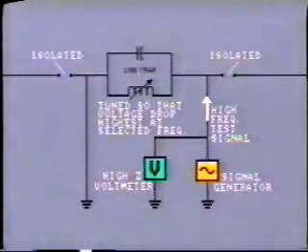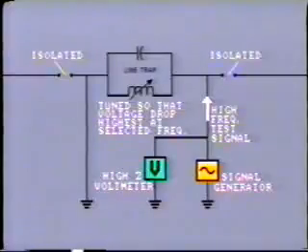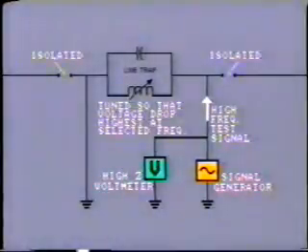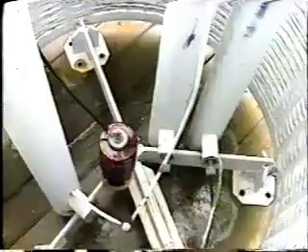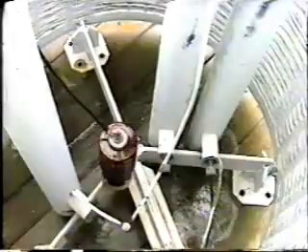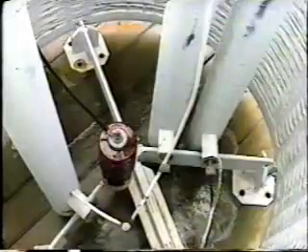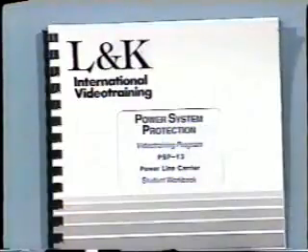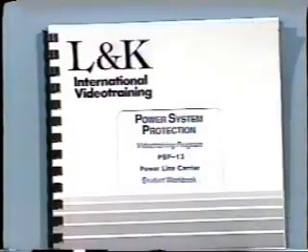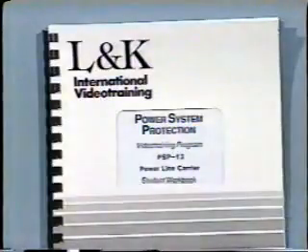Where possible, the line trap should be disconnected on both sides, so as to prevent interference to the test from the line capacitance. Preferably, it should be removed completely and suspended, so as to be completely free of any interference. All of the tuning equipment, capacitors, resistors, inductors, is located inside the main inductor coil. A typical utility company test procedure is included in your workbook. Make sure you have access to instruction manuals and your own company procedures before commencing any test or tuning of line traps.